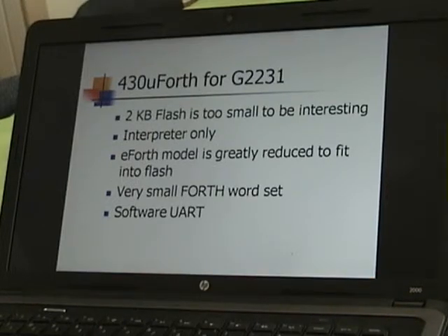So 430 microForth, that's what I did last year with the G2231. Because we only got 2 kilobytes of flash, I had to throw away lots of things, including the compiler. So this implementation was an interpreter-only version.